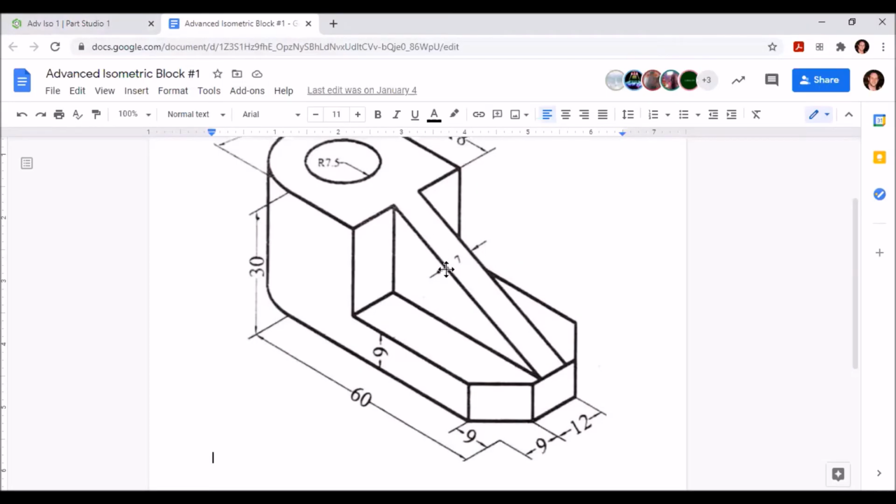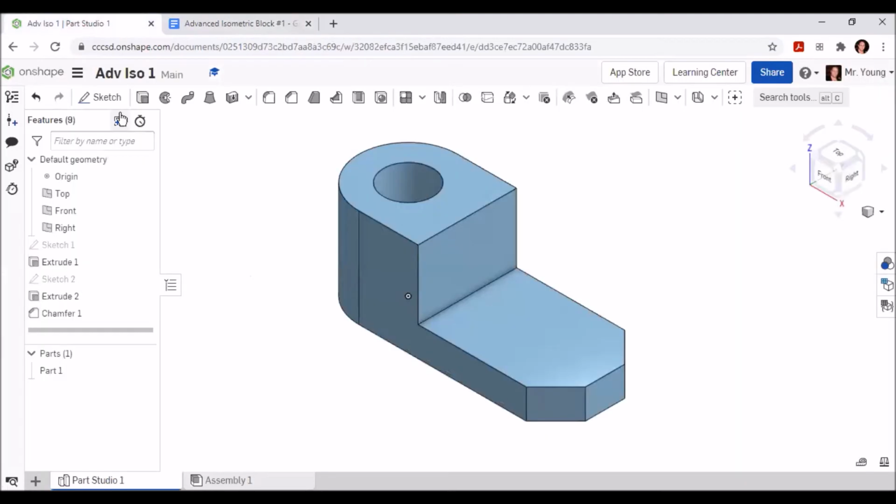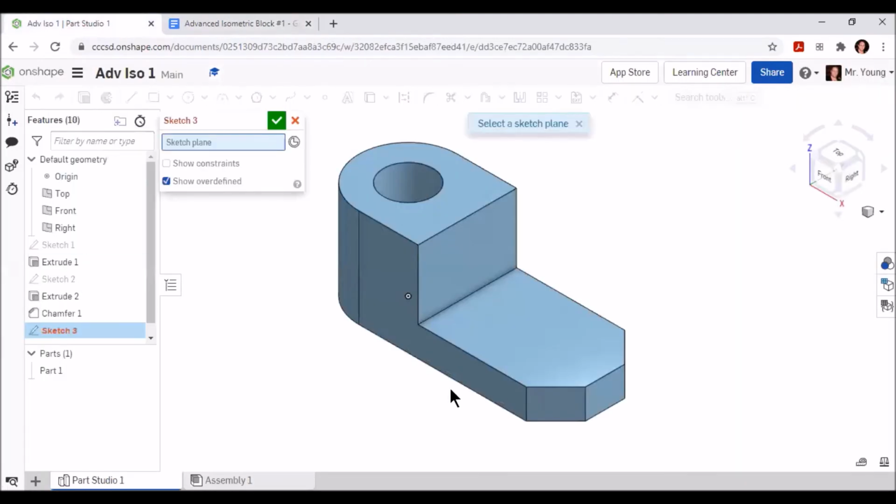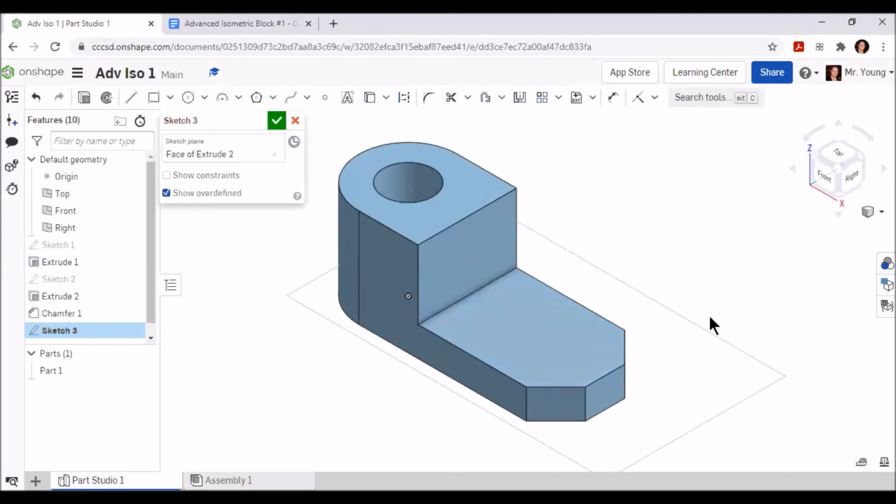Look at some dimensions that are going to be applied. 7 inches is the appropriate width for this angled wall. It's centered on the object. Let's start by creating a sketch on top of the new base area we just created. Rotate to the top view of your Cartesian cube.